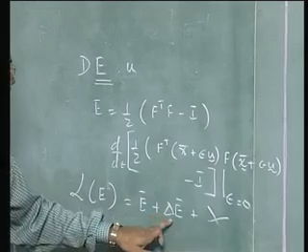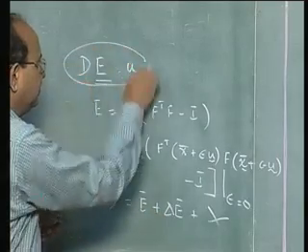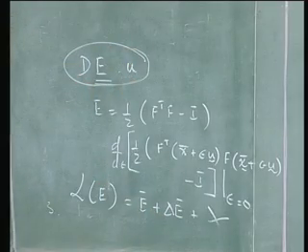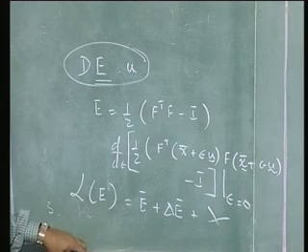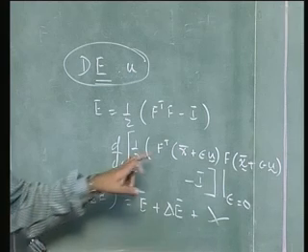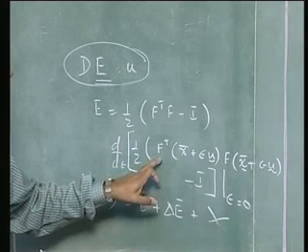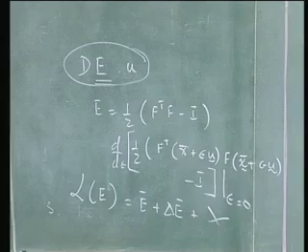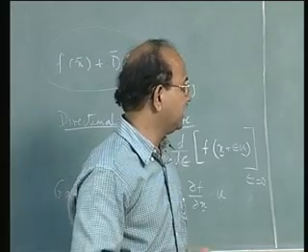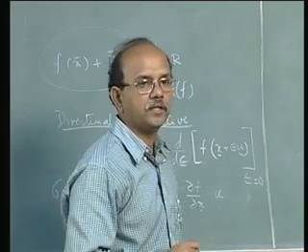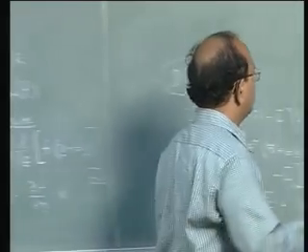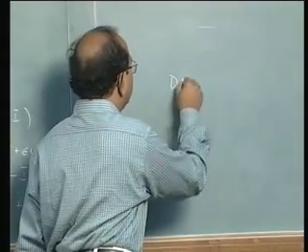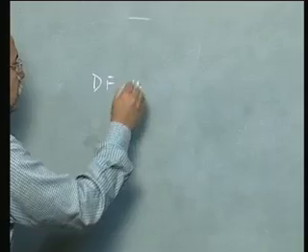This delta E bar is nothing but dE dot u. In order to do that, I have to calculate the linearized part of F, which is the deformation gradient tensor. So how do I do the linearized part of the deformation gradient tensor? Or in other words, what is dF dot, say, u?